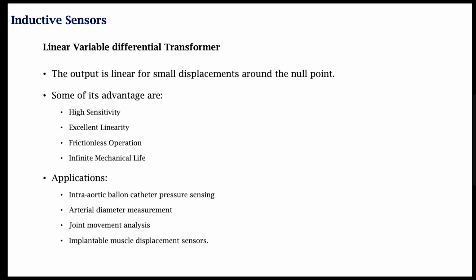The advantage is that this will be airtight and watertight, and because the seal is going to protect the core, there is going to be no corrosion or no disturbance to the core itself, giving a very long shelf life. So it will be highly reliable in harsh environments such as the human body. Remember, the human body presents a harsh environment for electrical measurement systems such as these.